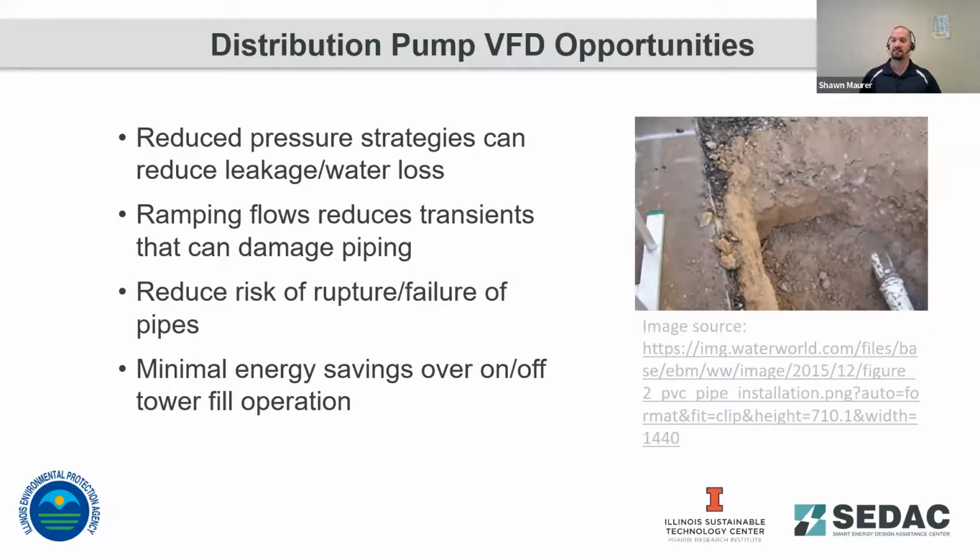On distribution systems, VFDs can be beneficial here, but a lot of times it's tied to operational strategies in your distribution network. If you can reduce the output pressure in your network, particularly during times of day when demand is lower, you don't need as high a pressure in the distribution network. You can reduce the pressure coming from your high service system, reduce the water level in storage water towers. There's a couple different strategies that can be employed to reduce the overall pressure during periods of low demand.